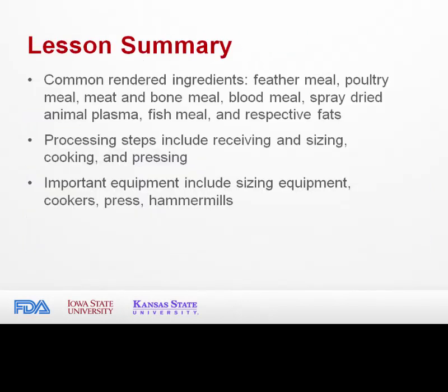In summary, we have identified common rendering ingredients as feather meal, poultry meal, meat and bone meal, blood meal, spray dried animal plasma, fish meal, poultry fat, beef tallow, choice white grease, and yellow grease. Rendering includes multiple steps, including receiving and sizing, cooking, and pressing prior to grinding. Of these steps, the cooking process is most pivotal.